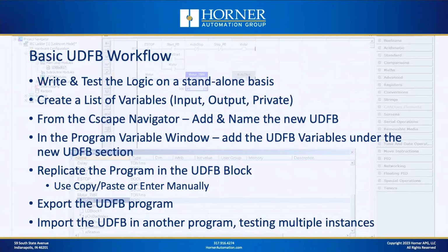Once you've got that where you want it, now it's time to take a look at the inputs and the outputs to come up with a list of variables to be used as inputs and outputs for the function block. And then the other variables involved that aren't inputs and outputs, they'll end up being internal or private variables used by the UDFB, but not necessarily accessible from the outside world or from the rest of the program.